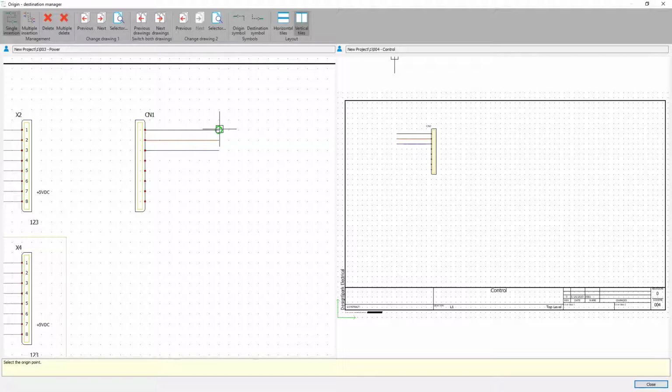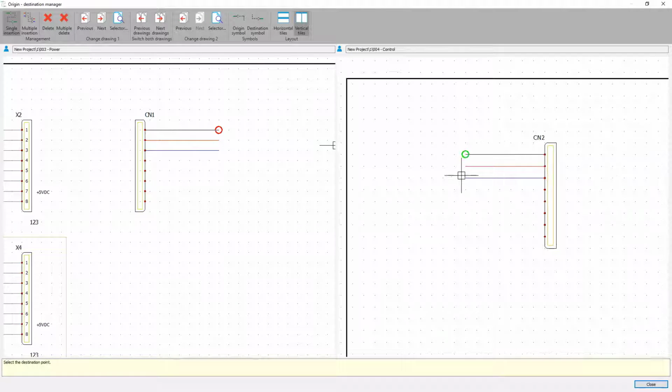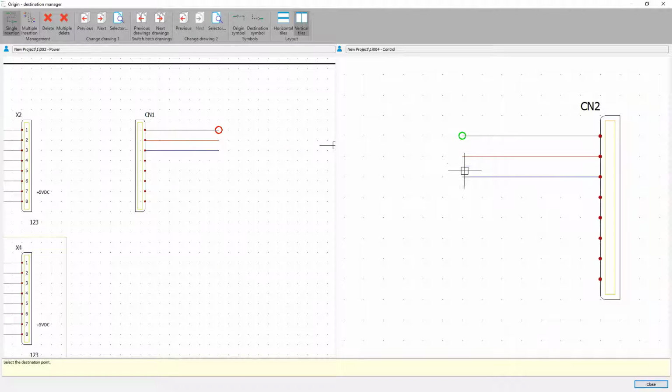And I'm going to go ahead and select this. Even though it's black, it's the white wire that we created in one of the previous videos. And I'm going to go ahead and try to connect it to my opposing page. Now, if you notice, when I scroll down to the blue or the red wire, it does not let me connect to those wires, and that is because these are different wire styles. It knows and recognizes the different properties for these wire types. So it's a nice little built-in design rule check for us. If we're trying to race and get a schematic done, it will not let us connect different wire types.